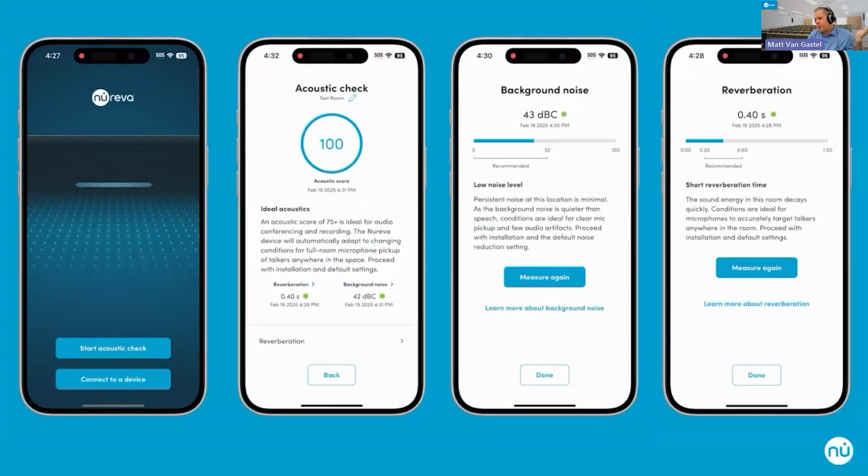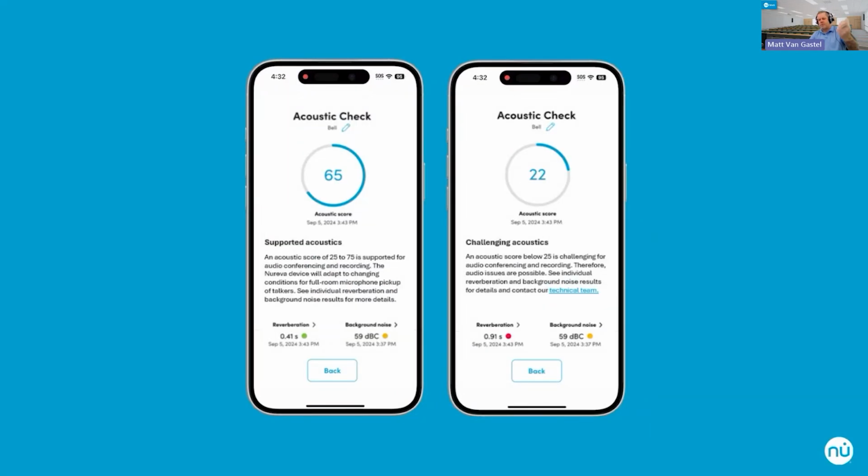But what happens if things go a little sideways, if it's not quite as good? Well, here's a few examples to take a look at. So in this example, we've got pretty decent reverberation time, but our background noise is high, 59 dBc. This is telling me that you likely have a source of noise in the room, something like an air conditioner or similar. Now, the other score is going to tell the tale of what you can expect to see in a really large space, possibly a common area with a lot of background noise. Neither score is fantastic. The one on the left is a little bit better.